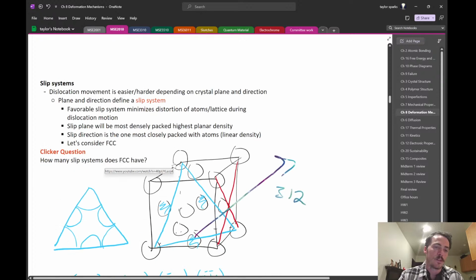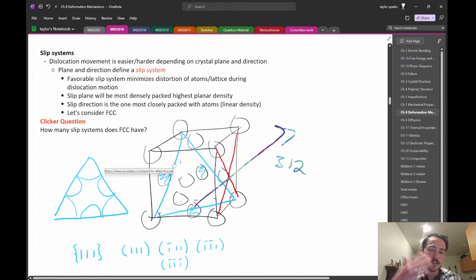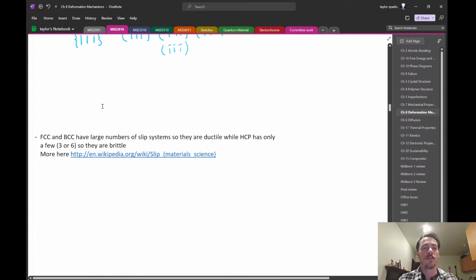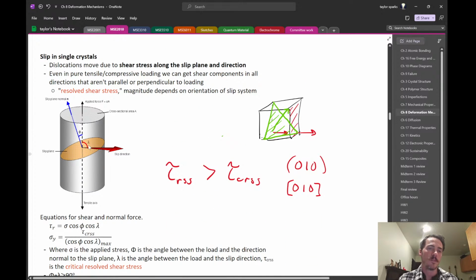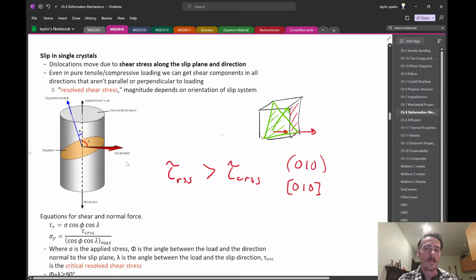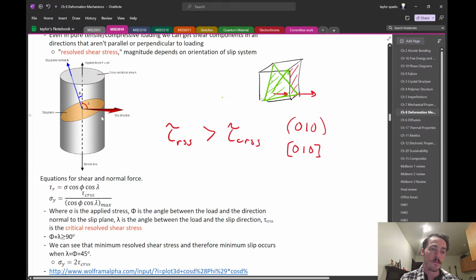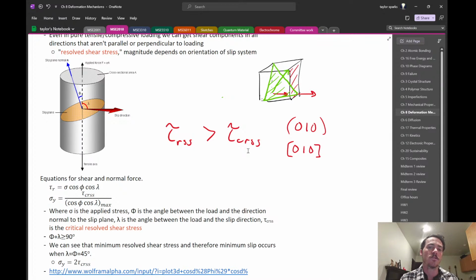So, for example, if we scroll down, first we were talking about dislocation and dislocation movement, which led to a discussion about slip systems, where you get dislocation movement specifically on certain planes. And we did learn about an equation here. It's called Schmidt's law. It was this idea of slip in single crystals: if you can calculate the resolved stress and compare that to the critical resolved shear stress, which will make it start sliding, then you can decide whether or not an applied stress will cause slipping on that plane in that direction.